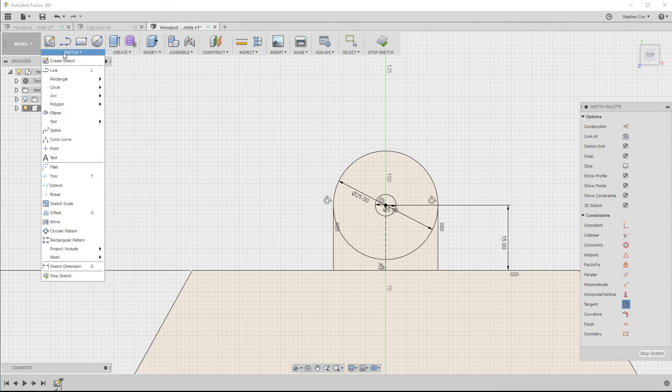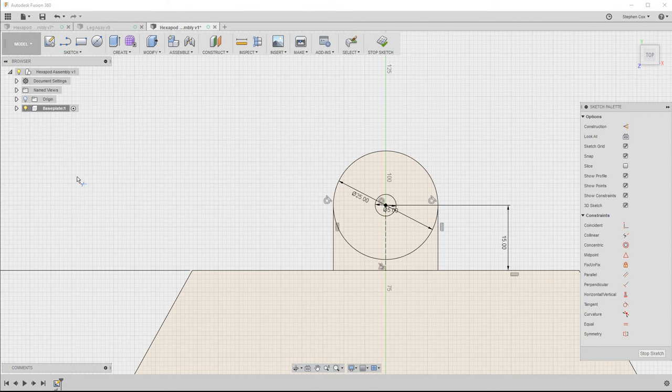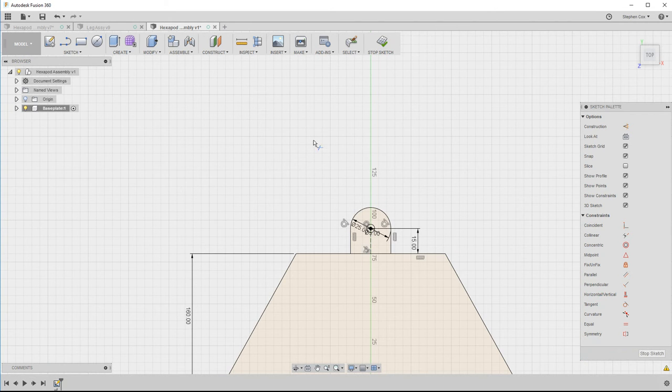So the other thing I can do at this stage is if I go to this lower part of the sketch menu, there's an item here called trim. I can actually trim out these particular pieces of sketch geometry. So I don't really need those. I'm going to trim those out. So that's now gone.